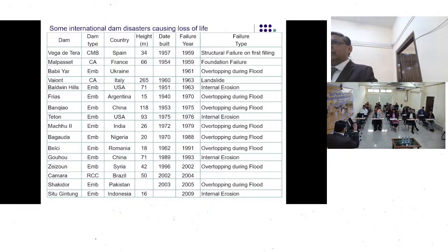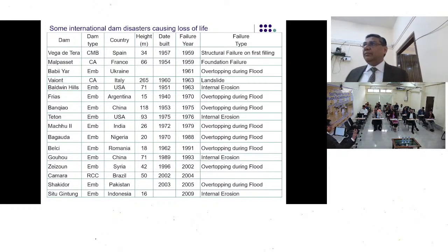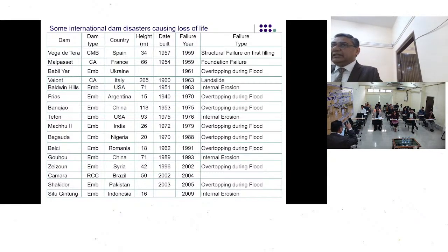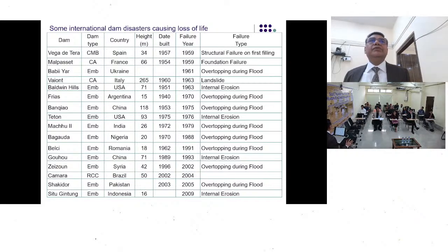So even though in the design or in the drawing we feel that okay, the structure is uniform, actually it is not uniform, and that non-uniform structure is now subjected to a constant water load. The profile is also variable. The valley, you don't get a square valley, right? So you will be having a U-shaped or a V-shaped valley, and so the profile is also variable. The load which is coming at different sections of the dam is also variable, and so it is going to be subjected to different types of forces: lateral forces, horizontal forces, vertical forces.